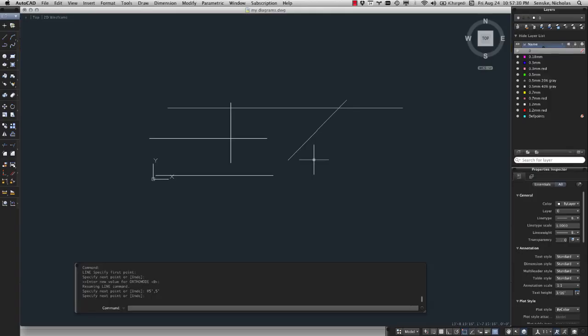But when you draw it, draw it as it is, okay? That's because, again, you can always change the scale when you plot. If you do the calculations here, it's going to mess things up later, okay? So just draw things as they are, even if they're ginormous, and even if they're small. Just going to save you trouble later.